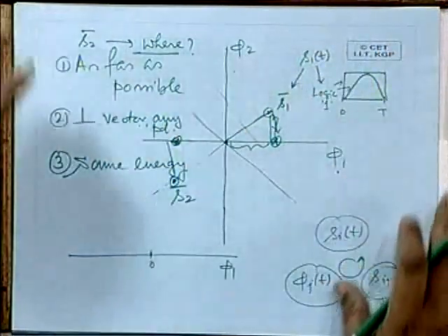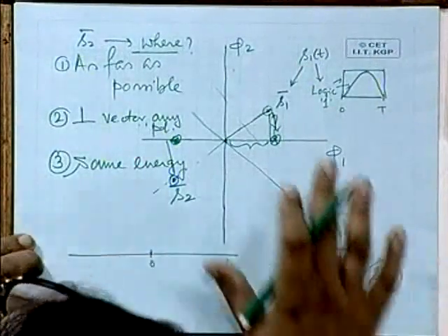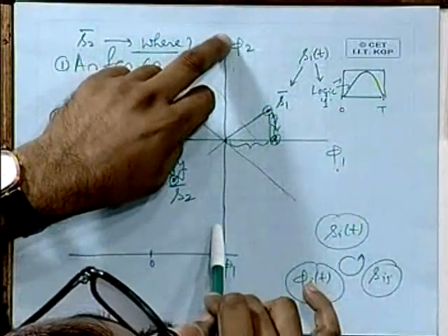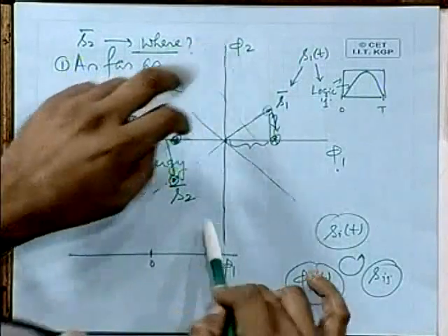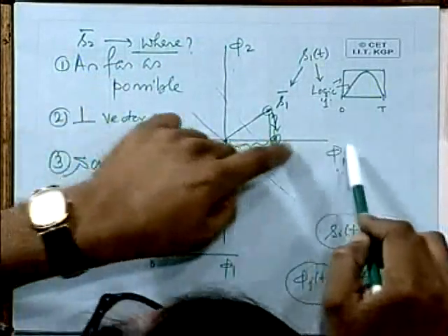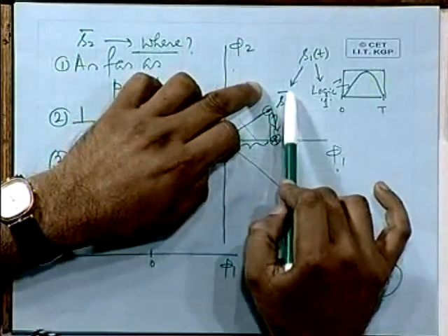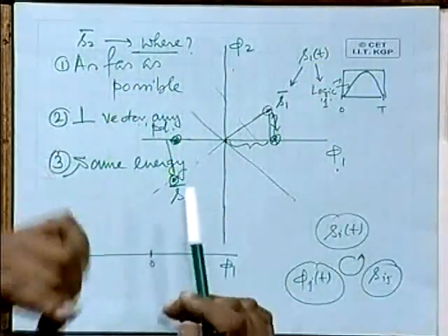But anyway, this discussion is not very important practically for BPSK. More so because in the receiver there is a carrier phase recovery circuitry if you are going for coherent demodulation. But for receiver description, because there may be a phase offset, this description of two dimensional signal space, even though there are only 2 points, could be as well shown on the same axis, a single axis, is a good one. Anyway, come back to our question really.